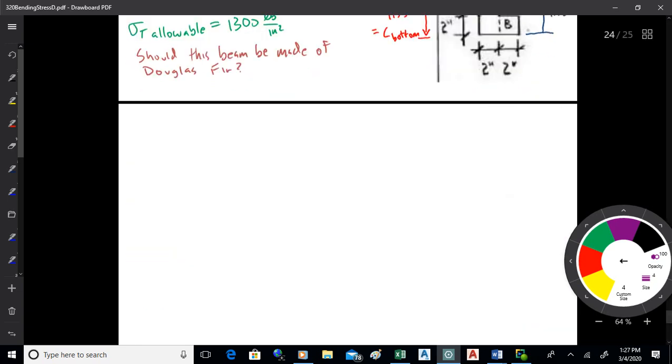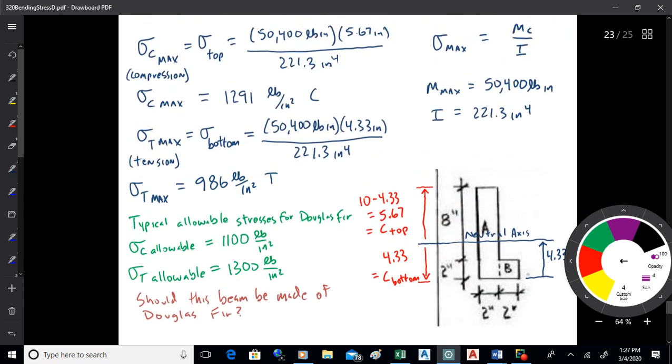Okay, so that's the basic way of analyzing that. That's one of the things that you design beams for and analyze them for, bending stress. Now there's another thing too, and that's shear. I mentioned that you analyze just the edge because that's where the maximum C is, and that's where the stresses get maximized.